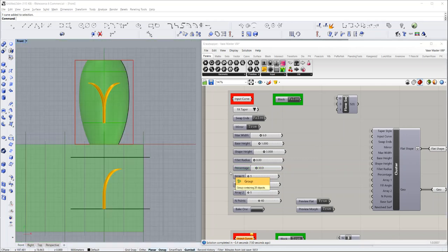Okay, the next thing we want to take a look at is how these arrays work. Right now this says array 1 is one item. And by the way, the one item means with the mirror included. And it says a fill angle of 30 degrees goes with that. So let's change this to something like 3. So we're going to create this array of 3 items that fills 30 degrees.